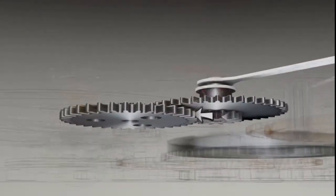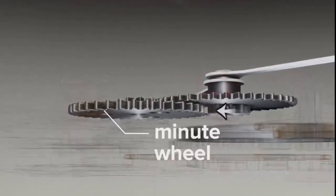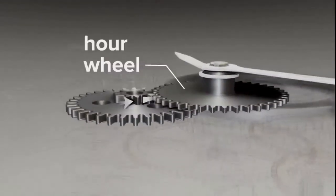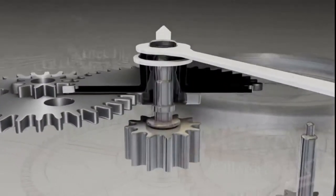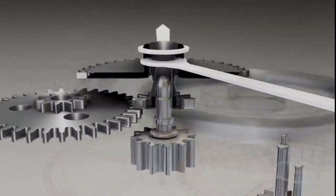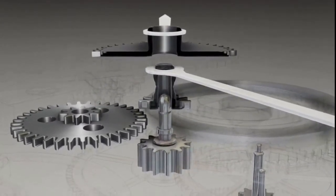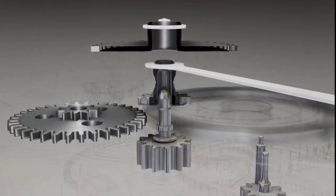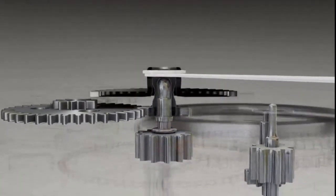This speed reduction is achieved as power flows from the cannon pinion through the minute wheel to the hour wheel. The cannon pinion and hour wheel are press-fit to the pinions that support them. This means that with enough force, they can be moved for time setting without disturbing the rigid underlying wheel train that otherwise drives them.